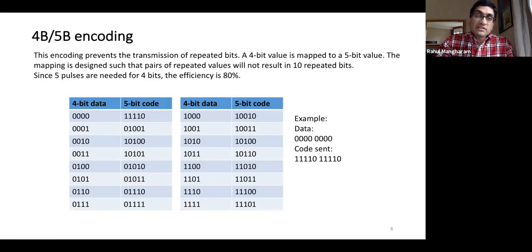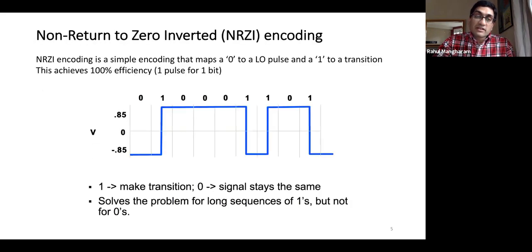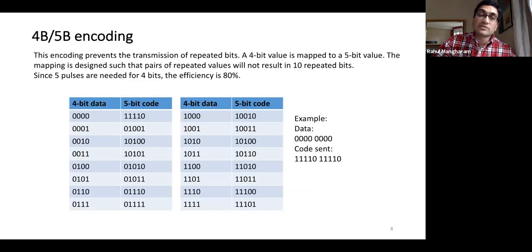So that brings us to the next part and says, okay, wait. In this case, we came to half a solution that whenever we have a 1, we introduce a transition. We are forcing a transition. That means if I have a back-to-back 1 over here, I have a transition. And then we can say, hey, what we really want is a signal where we always introduce some transitions. So if I have all zeros, I will map that to a slightly longer bit vector, but I will actually introduce a lot of transitions over here.